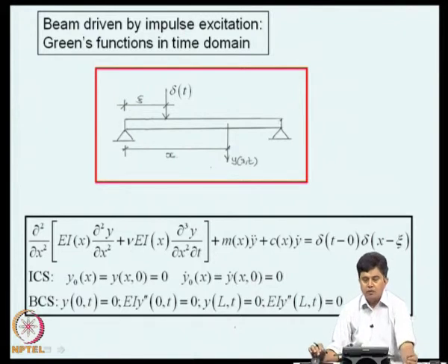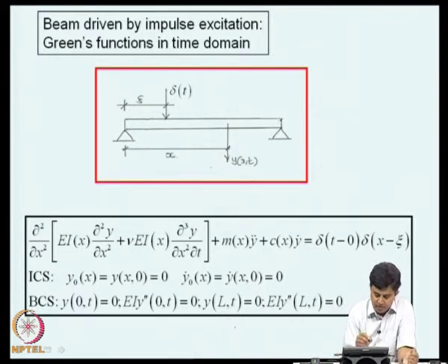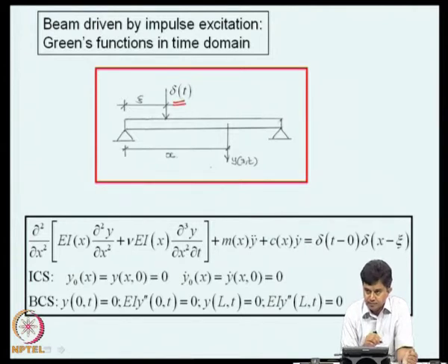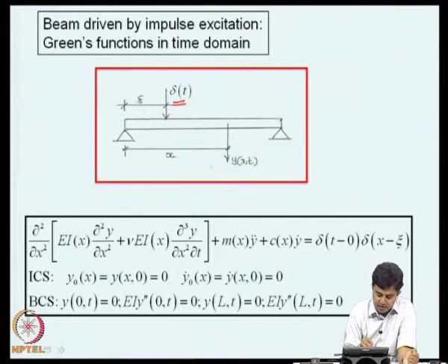Now, we will look at these problems in time domain. Instead of applying a unit harmonic load, if I were to apply a unit impulse load at x equal to psi, and again ask the question, what is the response at this point x, at a distance x from this end.